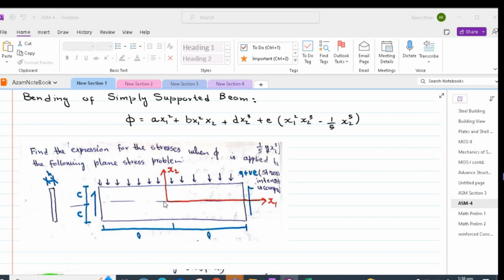Then for a rectangular plate, say, we could have a stress function having 8 integration constants. These integration constants will be worked out using the 8 boundary conditions. If we opt for a stress function which has got more terms and correspondingly more constants, then we will have to impose some other or some additional conditions to work out our constants.